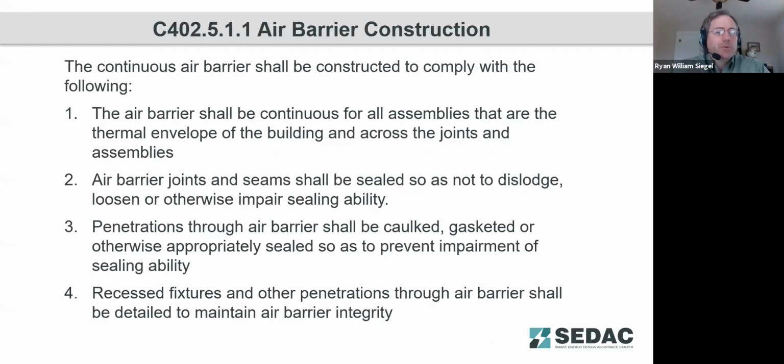So as we're going through the air barriers, making sure that we do have continuous air barriers and being able to verify the continuity of the air barriers, because air leakage not only loses energy, but commonly will bring moisture and vapor with it through leaks. And so if you do end up with problems in the air barriers, that can lead to substantial issues of moisture, which can lead to mold and mildew. So having a continuous air barrier is very important.